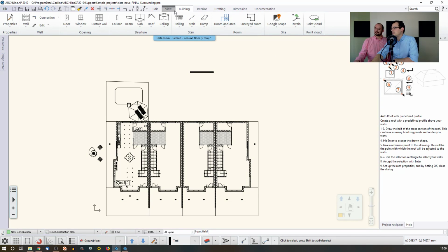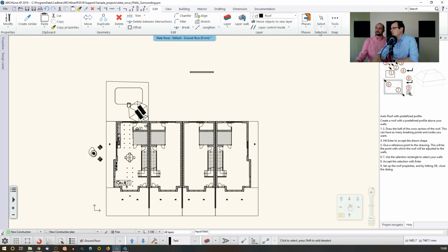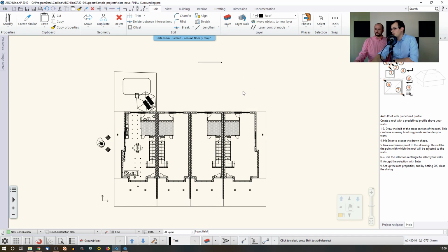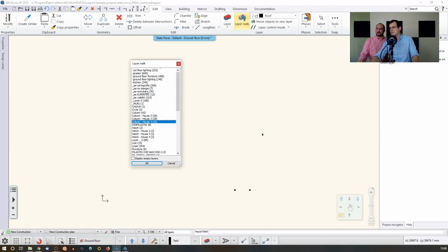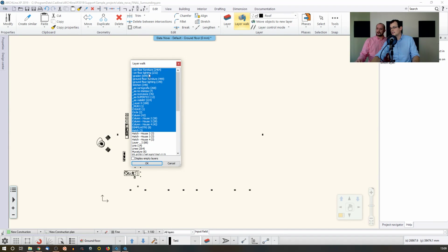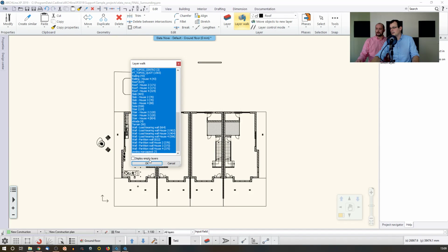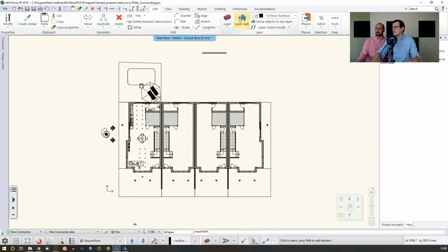Let's say, what would be a tool that will be used quite frequently? The layer walk, maybe. For those of you who haven't seen it, the layer walk is able to enable and disable certain elements that you want to work on. I use this a lot. If you want to switch between the layers very easily, that's the way to do it. When you make combinations of different parts, you can enable back the whole thing. So let's say you want this layer walk to be available at a very conveniently reachable status. Let's say Control, Shift, and W. That's something I can do with one hand, and that's very easy.